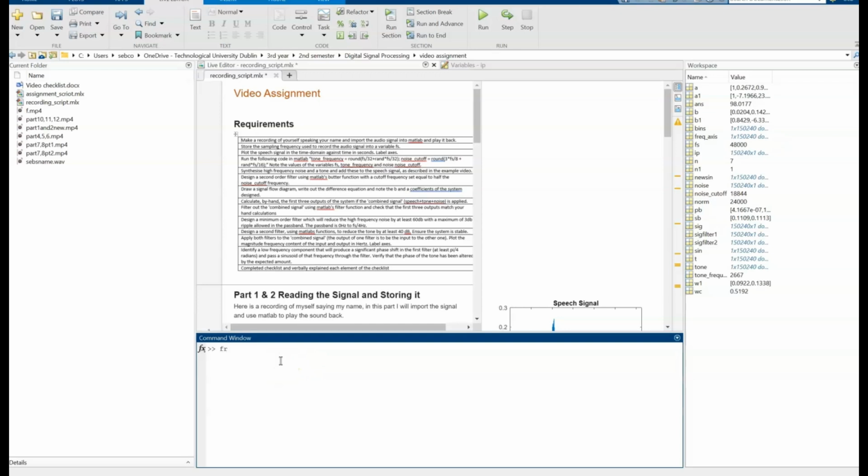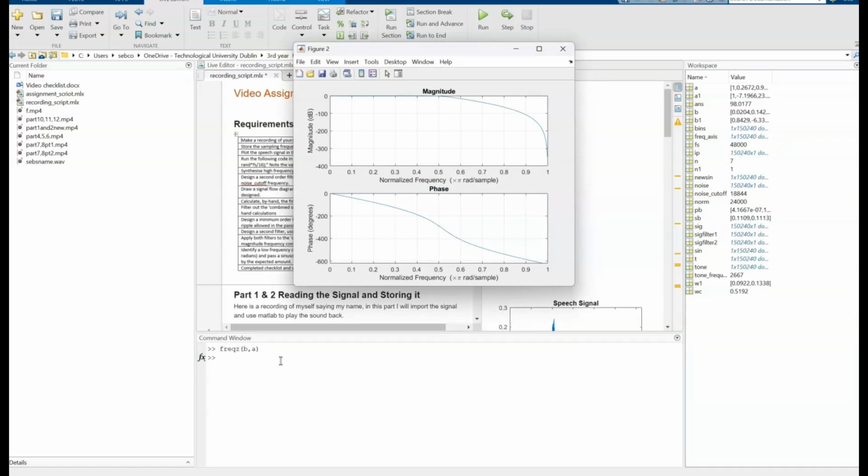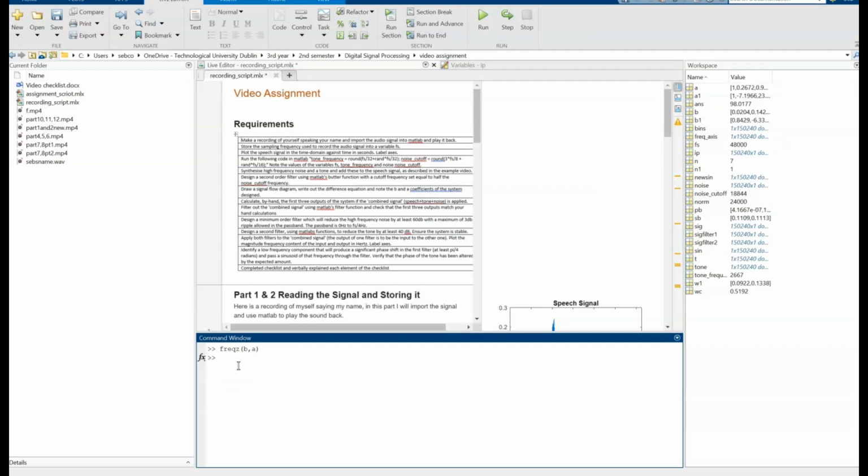So we'll start with the freqz function, then the b and a coefficients should stay the same. Alright, and then we want a 45 degrees. So around 0.117. So 0.117 times fs over 2, we're just getting it back into hertz here.